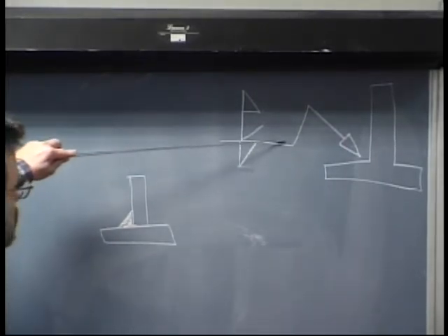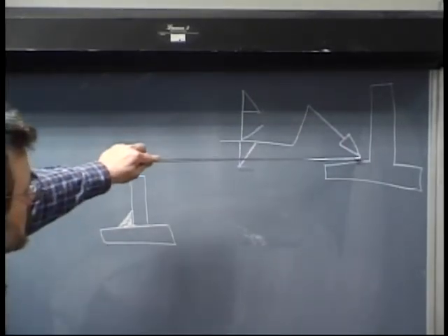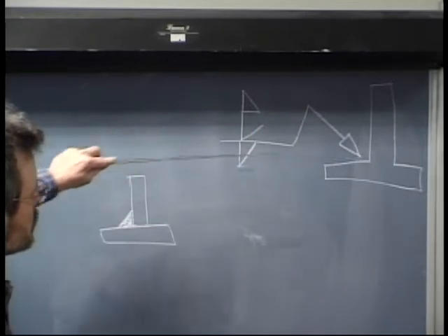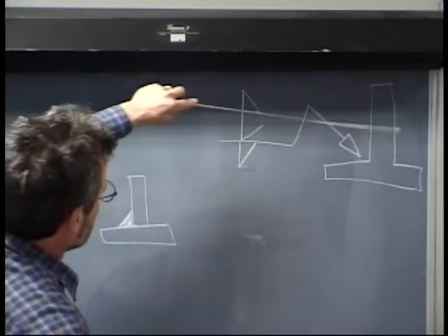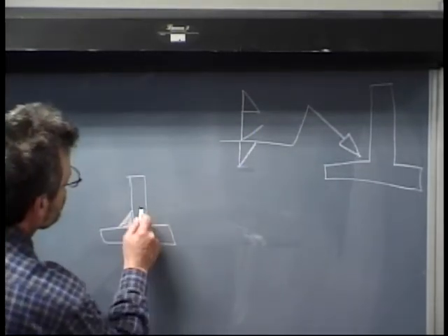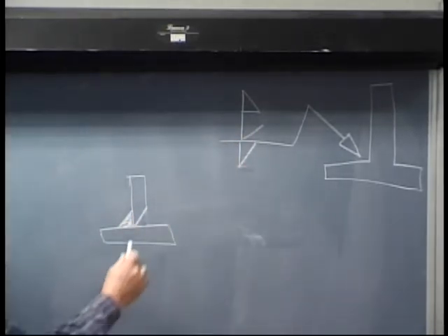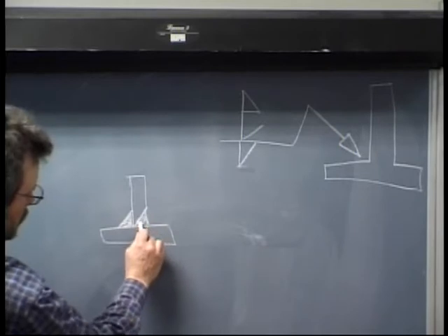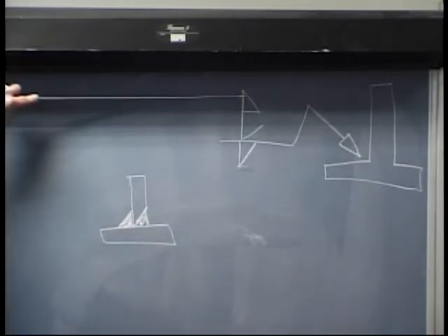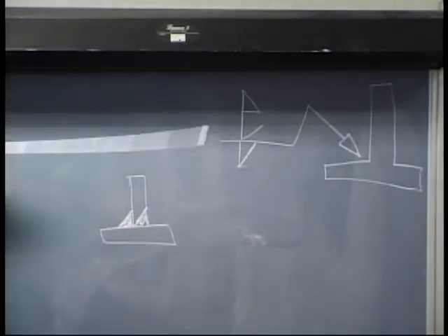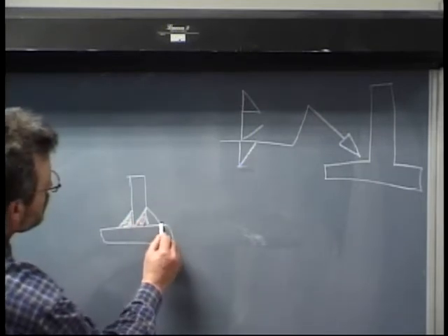This is pointing towards the arrow side. Therefore, on the other side, back over here, we want a V groove. So we would put a single V groove, and that would be a weld. But then on top of that, our last operation, reading from the reference line out, would be another fillet weld. So there's what we have.